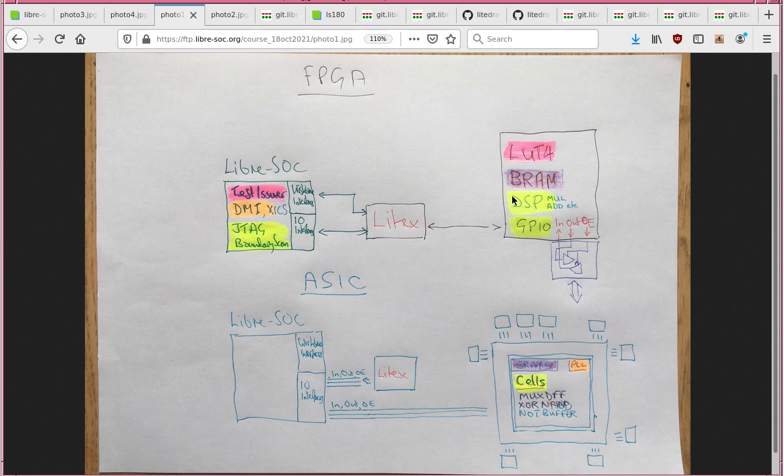You also have DFFs, which are latches, and typically the more advanced FPGAs will also have a DSP. Right? And the DSP will have multiply and add, etc., because implementing multiply takes a massive number of gates. It's just a waste of resources, a waste of LUT4s. You're better off doing it in a very efficient manner as a dedicated DSP block. And then you have GPIO of different types.